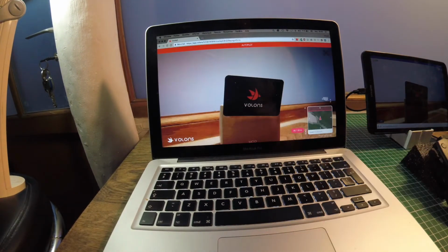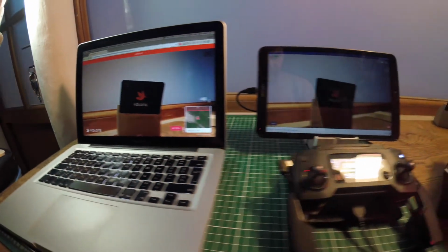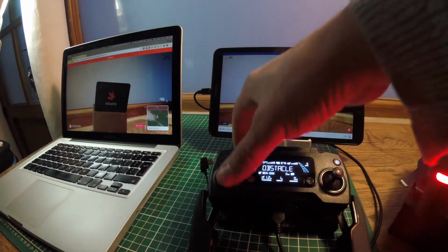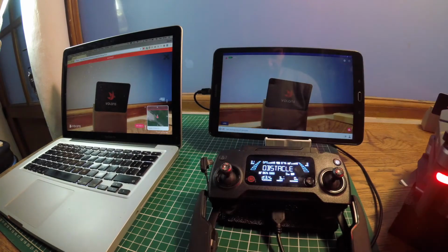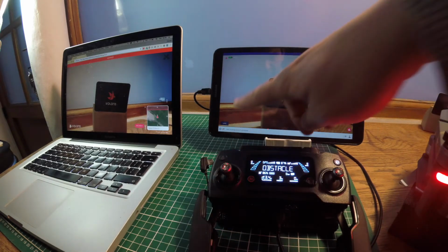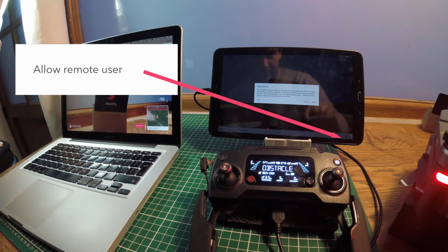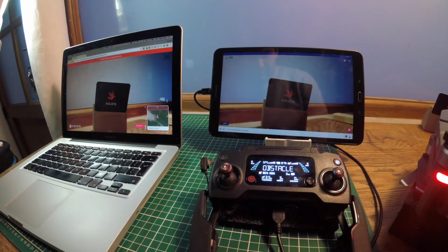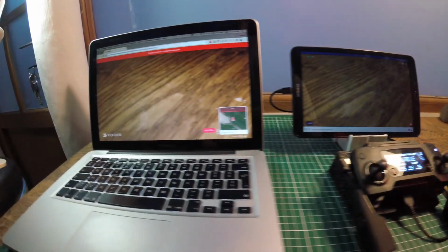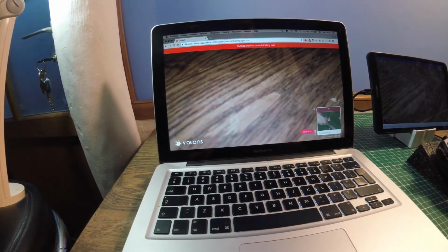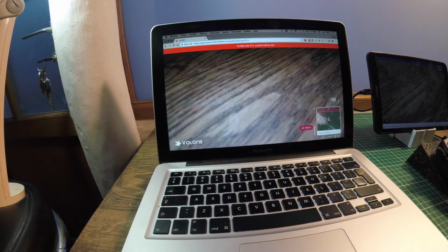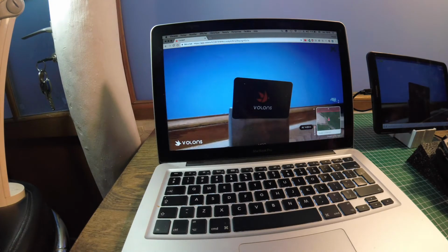The aircraft can be controlled with the remote control as usual. The limits defined on the previous screen only affect the remote user on the computer. At any time, we can allow the remote user to pilot the aircraft. As the aircraft is outside of the previously defined area, it will enter it in a straight line. On the remote user side, as long as the autopilot message is visible at the top, controls will not be active.